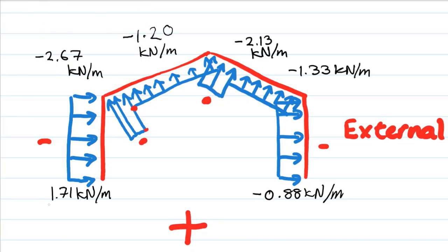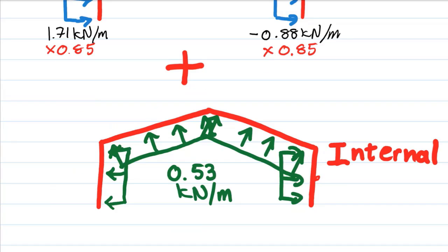And just remember now, if we are analyzing the whole thing, this should be multiplied by 0.85, and that should be multiplied by 0.85, and then once again you've got your high pressures at the corners, and then your pressure on zone D, suction on zone E. And here we have, with the internal pressure coefficient, everything's pushing out because we took the plus 0.2 CPI value and then applied it throughout.